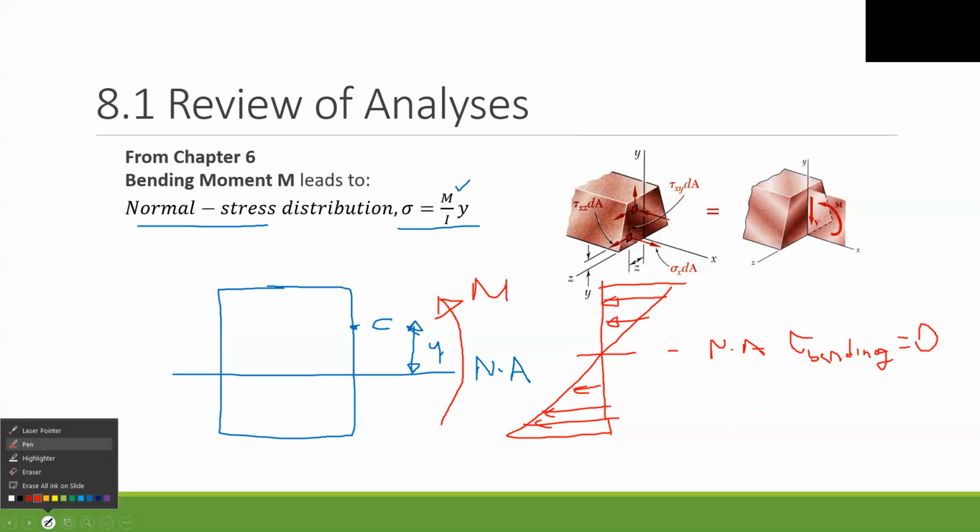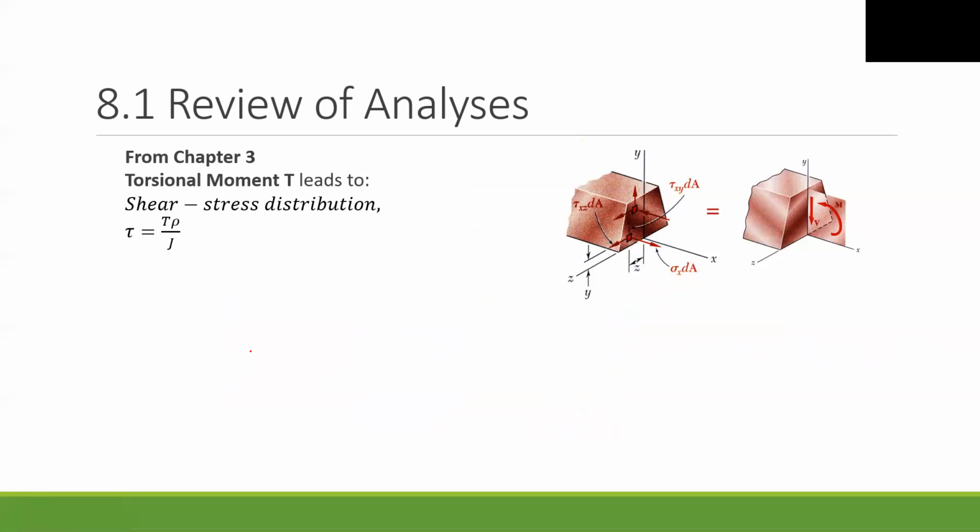You know, this terminology, I thought you already know these terms. I am explaining the stresses in order to remind you, in order to remember. Also, one term is remaining. If we have a torsional moment, actually torsional moment for circular shapes, not only other types of shape, because torsional moment causes both shear stress and normal stresses, but unfortunately the calculation of normal stresses due to the torsional moment is a little bit complicated.